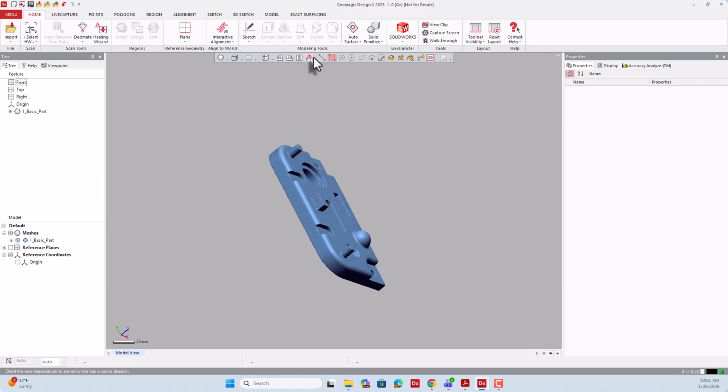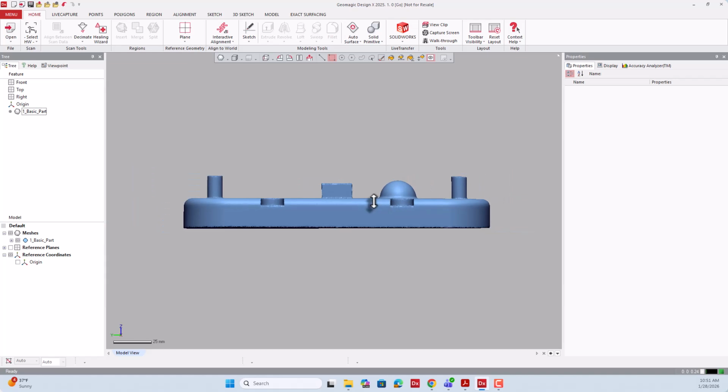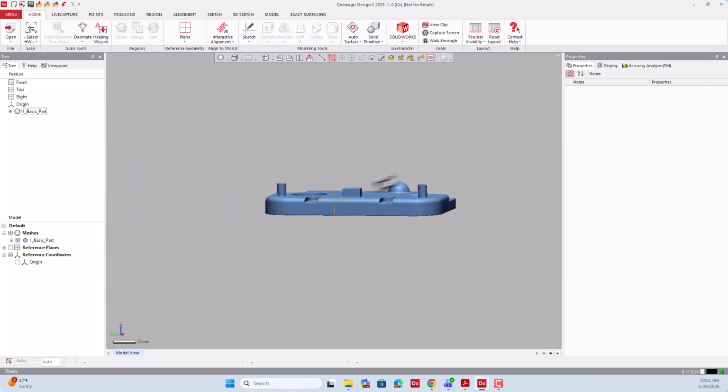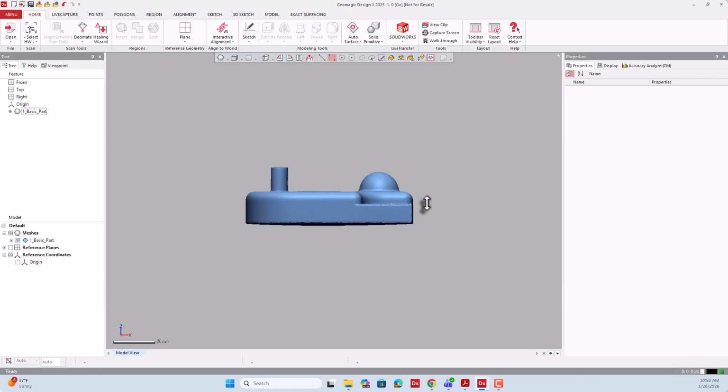And likewise, the next icon that we have is the normal to icon. So this is to orient it to the normal direction. So you can select that particular button, and let us say you want to orient the model normal to this face, and you click on that triangle, and automatically you can see that the body is oriented to that direction. So to show it again, you can hover over this particular mode, select that mode, and then click, and the body would automatically be rotated to that particular orientation.